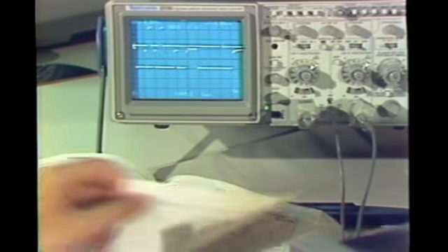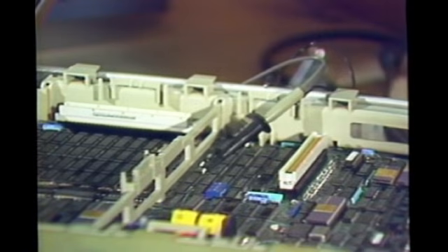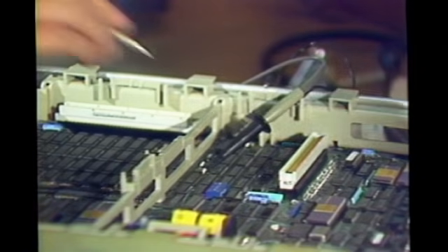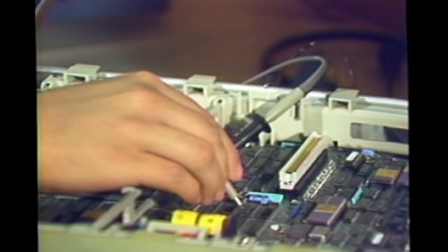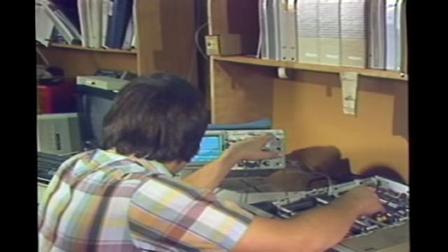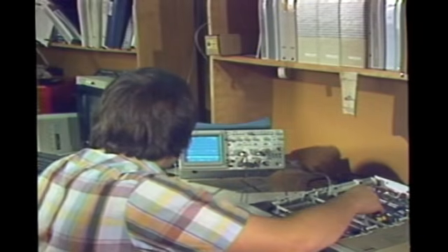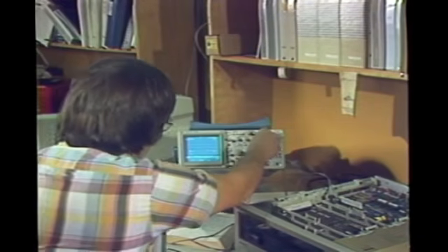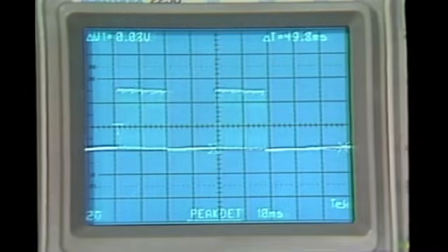Seeing what happened before or after a particular signal event occurs can be essential when designing or troubleshooting electronic devices. Sometimes the circuit glitches just before the desired event occurs, causing problems in following circuits. Or the signal's leading edge doesn't have the proper shape or rise time. Or a circuit may take too long to settle after generating one signal event, or begin generating the next signal event too soon. In any of these examples, a digital storage oscilloscope provides the option of viewing the waveform before or after the trigger point.